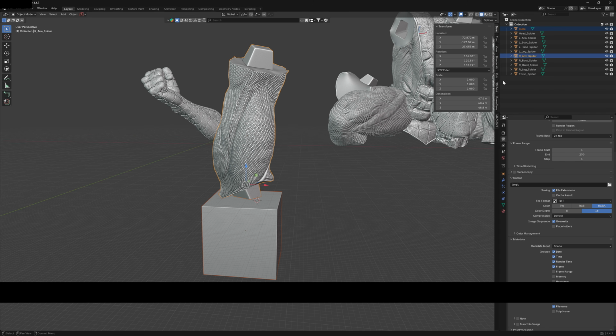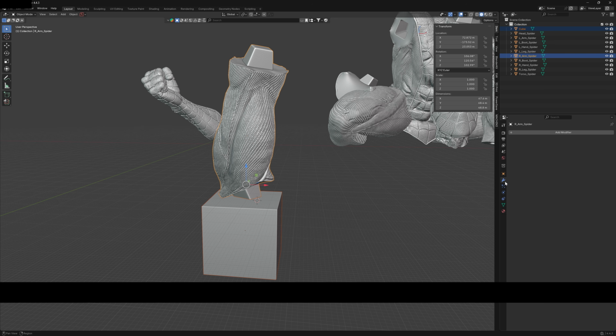You're going to do something called a boolean, which you can do with a modifier here, and you can add a generator and boolean. But the bool tool is more useful, actually. It just does it quicker, I think. You can take things away from one object to another. You can merge objects in different ways, completely or just the parts that overlap, or you can slice, so it just deletes the parts that are overlapping. With a little bit of playing about with it, you'll see the difference. You'll know which ones to use.